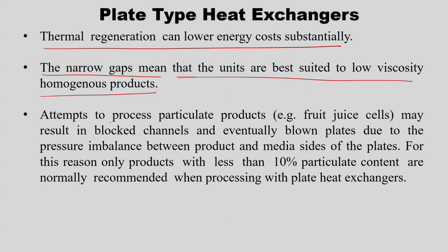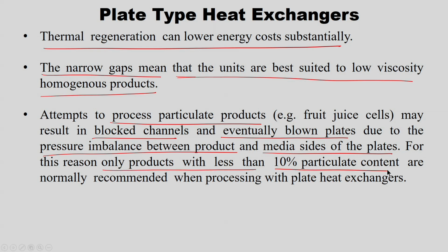Attempts to process particulate products, for example fruit juices with pulp, may result in blocked channels and eventually blown plates due to the pressure imbalance between the product and the media sides of the plates. For this reason only products with less than 10% particulate content are normally recommended when processing with a plate type heat exchanger. So, this has to be kept in mind.